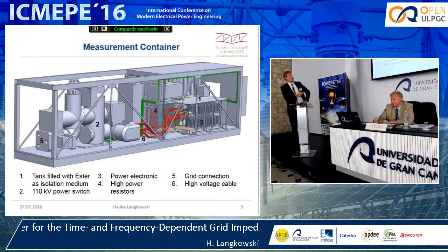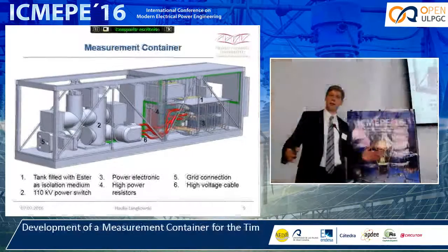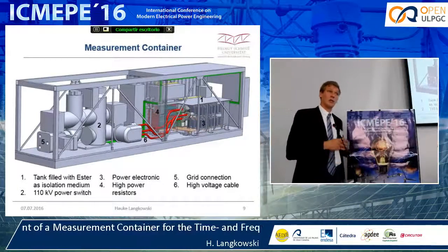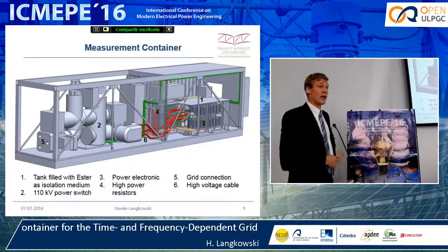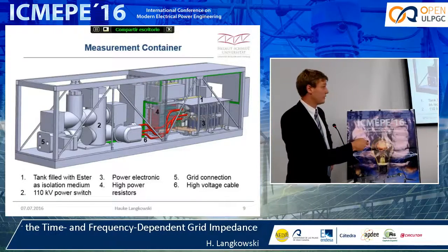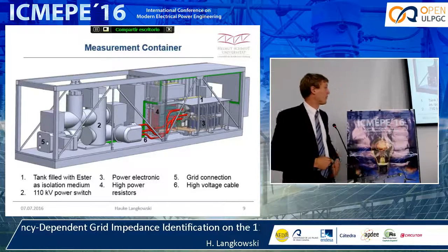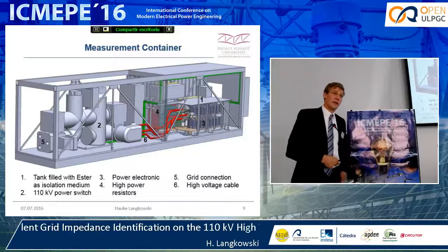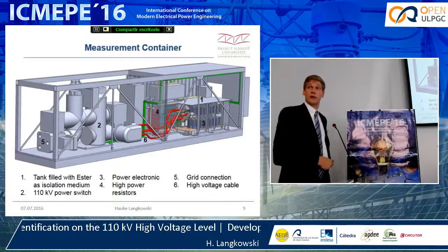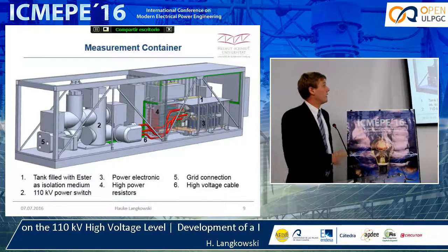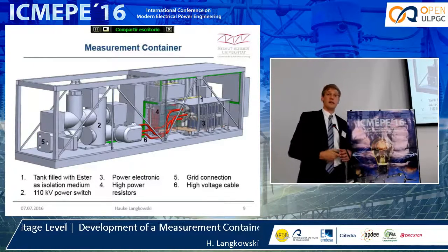Of course, we are having here very high voltages, 110 kV, so the distances between parts under voltage are very high. We cannot work with an air-insulated setup. In this tank we have the medium ester that is compared to oil that's being used in transformers. Ester is better in environmental aspects. So the whole tank, where there is the B6 diode bridge and also the IGBT and the load resistor here at the back, they are all in ester.